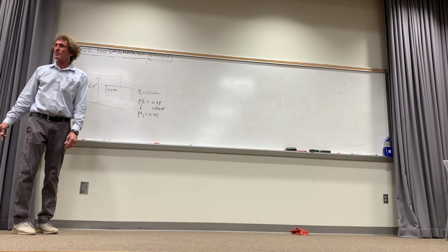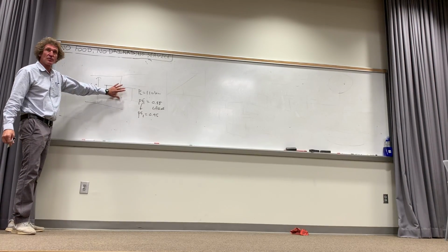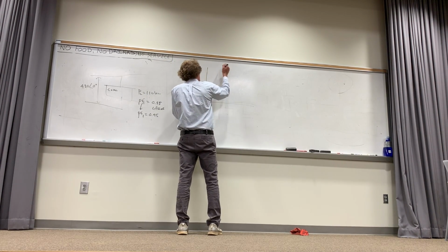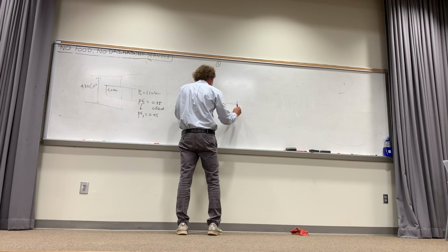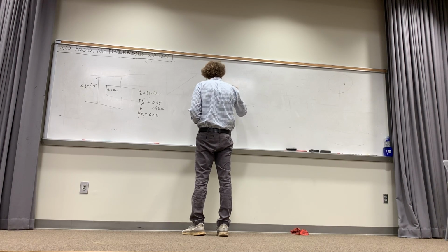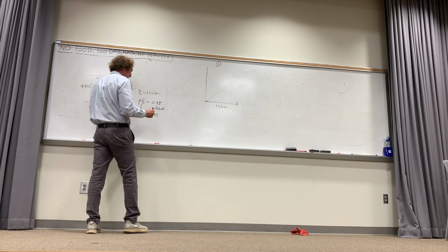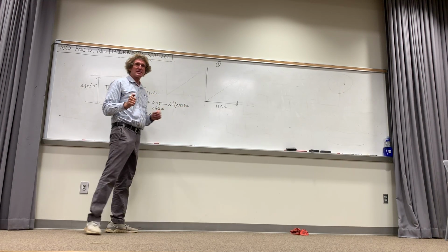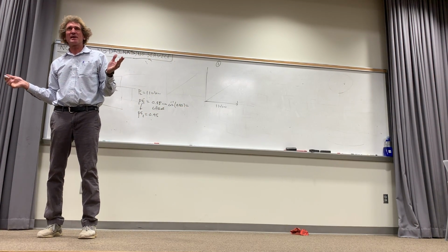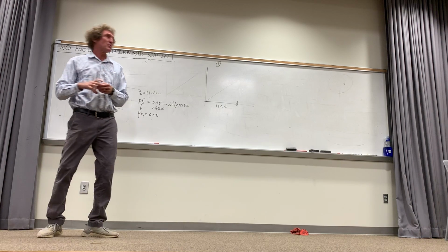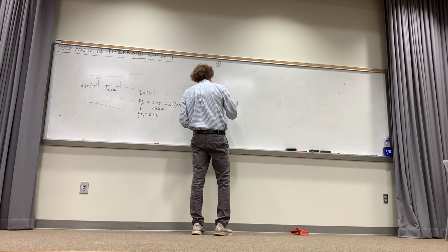First, I'm going to draw the power triangle associated with this as is. It looks like this. Call it 1. I have a real power, which never changes, of 110 kW. Now, I know the angle here would be the inverse cosine of 0.85. I want to say it's 29 or 26 degrees, I don't know. What is it? 31.78 degrees.